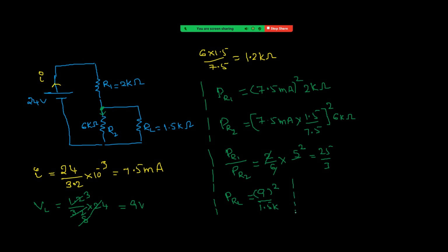Let us calculate now after interchanging. Let me see once VL. We made a calculation of VL already, 9, using that here. Now, if you interchange R1 and R2, that means now this becomes 6 kilo ohm and this becomes 2 kilo ohm. Then see what happens to the potential across this.